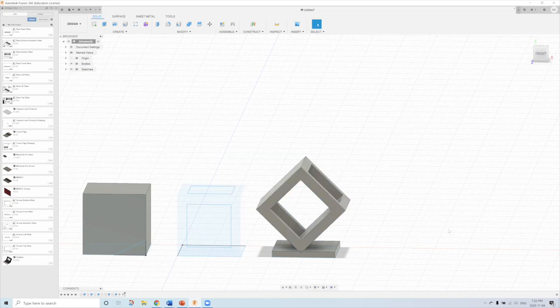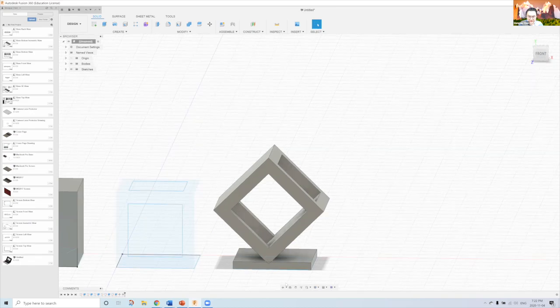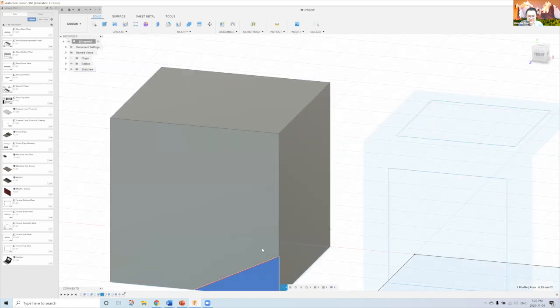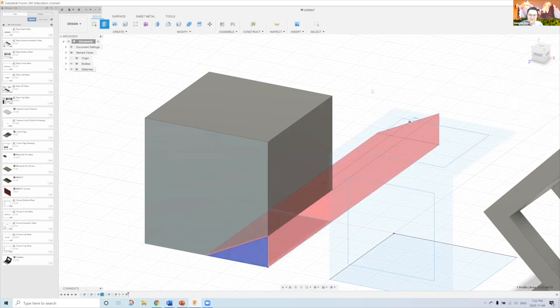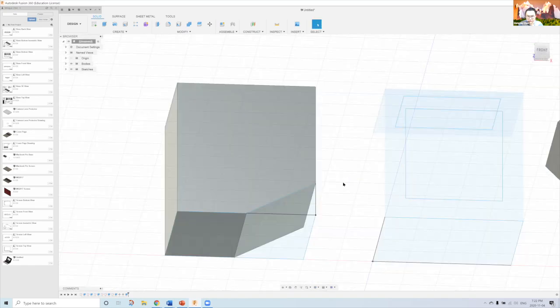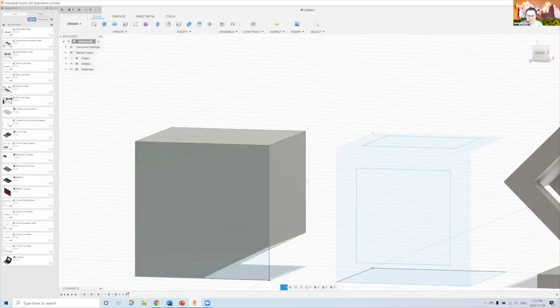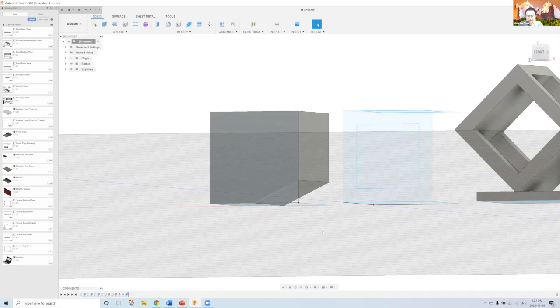Okay, cool. The next example I want to do is very large overhangs, right? Let me just extrude here. So this is a pretty large overhang on the bottom of the print, and you want to avoid something like this when you use an FDM 3D printer. So what you could do is implement supports here. You could reorient the print so that it's not on the downside of the print itself.